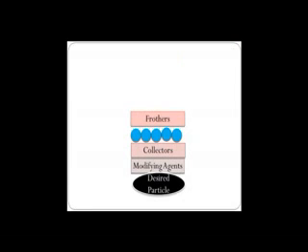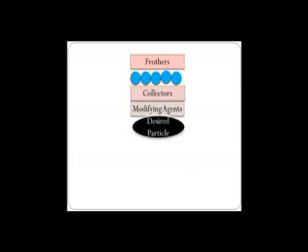Lastly, surface active chemicals called frothers coat the bubble surface and stabilize it by decreasing the surface tension of water. The surface active characteristic disrupts the surface water molecule attraction, thus weakening the surface. Weakening the surface tension will prevent the water from exerting too much force and allow the bubbles to retain their integrity. When the process is successful, the particulates, together with the bubbles, may float and may be recovered on top.